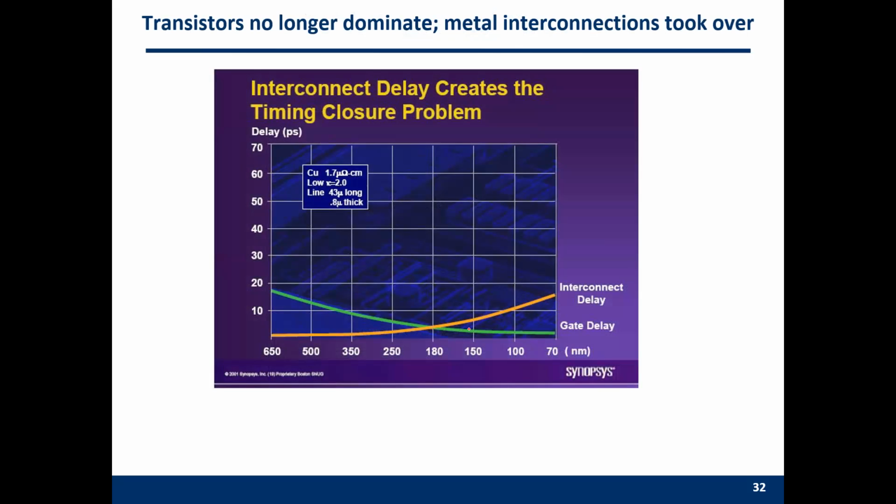In the traditional design, you can see we have a hex line, long line. The line distance becomes very long, very large. Longer distance indicates you have a larger resistance and capacitance. All of these factors will be converted into slow speed and long latency. So you can see that if the lines on the FPGA board are very long, then your FPGA cannot run at a very high frequency, and you will eventually have the power problem soon.